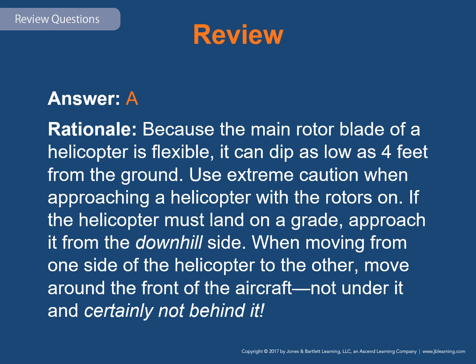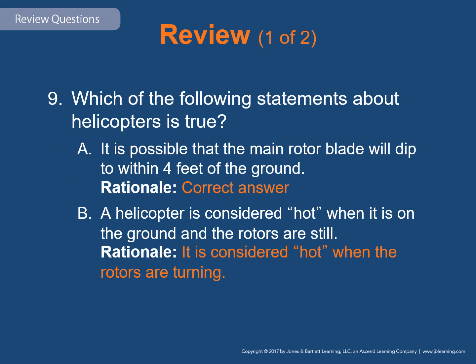If a helicopter must land on a grade, approach it from the downhill side. If you're moving from one side of the helicopter to the other, move around the front of the aircraft, never under it, and absolutely not behind it, because of the rear tail rotor, and then also you have exhaust ports. So never ever go behind the aircraft when it's in operation. Ever. I'm not going to cover the incorrect statements because they're all ludicrous and we know why they're incorrect. And we reviewed them by going over correct procedure just now.